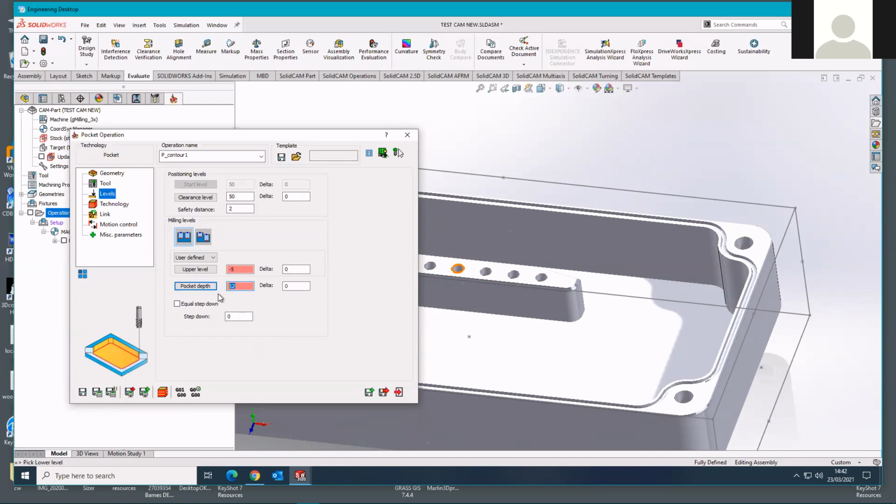Whereas alternatively, if I was just to type a number in here, which is what I'm doing now, that is not linked. That is just a static number. So that is not dynamically linked to anything. So if I was to change the model with the intention of machining the new version, the Mark II model, on every production run, that wouldn't come to pass.